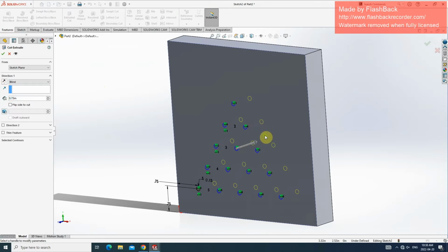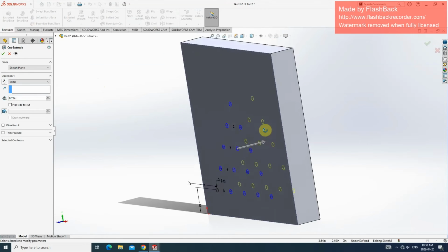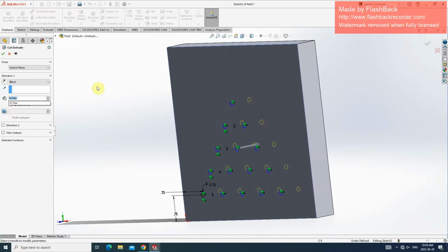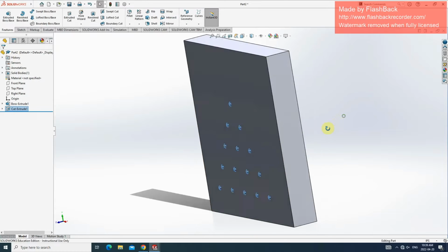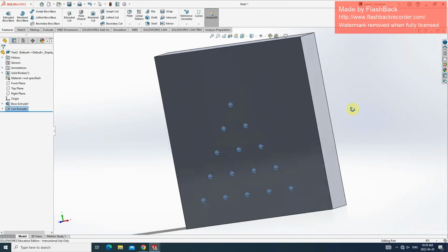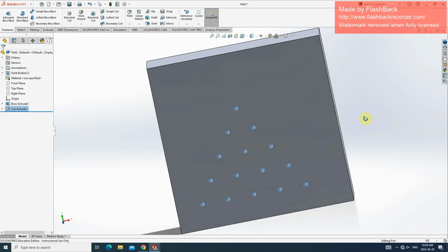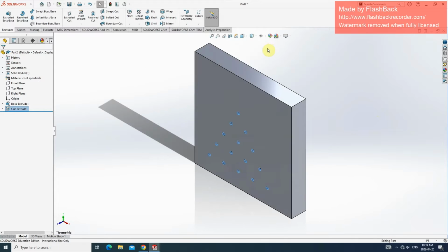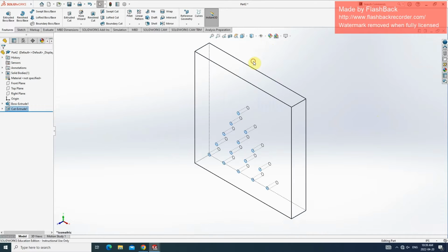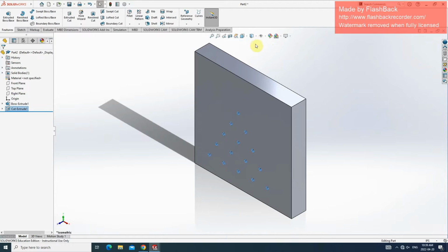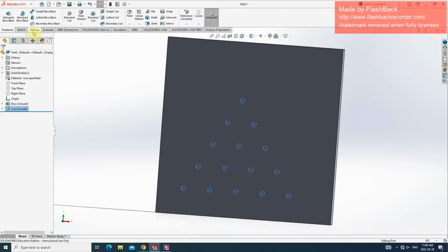You can rotate the square to see there's an arrow and the yellow circles are showing how much depth we're putting into our cut. The way to change that depth is in the left bar, insert 0.50 and then hit the green check mark. If you're wondering if it worked, you can hold down the mouse scroller and rotate it, or change the view to isometric and then take away the solid coloring. And you can see the dotted lines clearly show that we've made the extrusion.